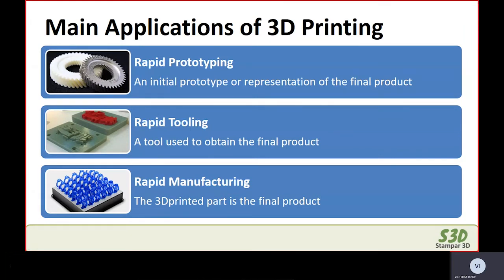So I think what the question is all about is how do you get a smooth surface finish? Like we said in the beginning, additive manufacturing is a layer by layer process. So the layering effect, we cannot really get rid of that because that is how the object is built. What we can do is, with our slicer settings, modify the thickness of this layer. The thinner the layer is, the smoother your resulting object will be.